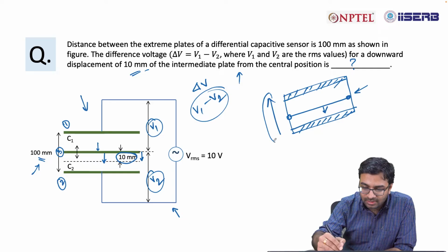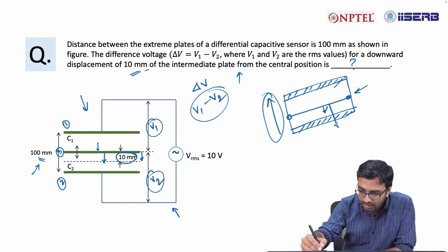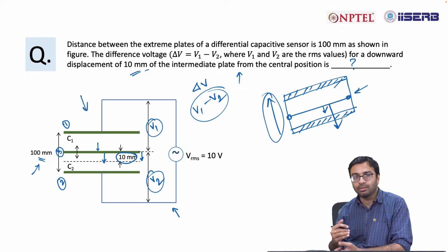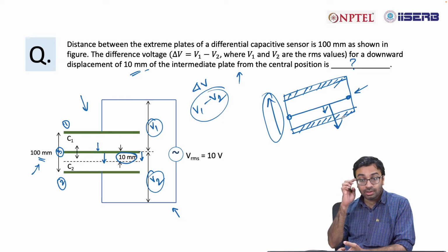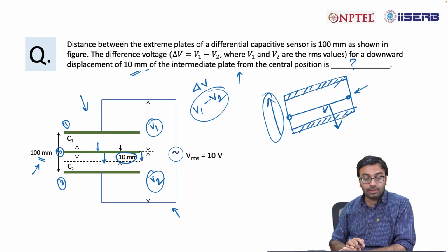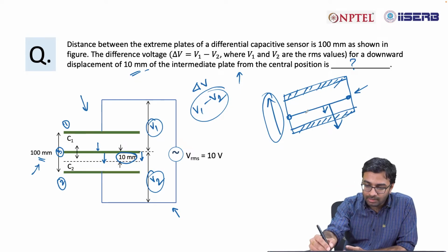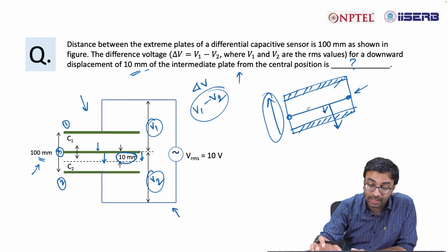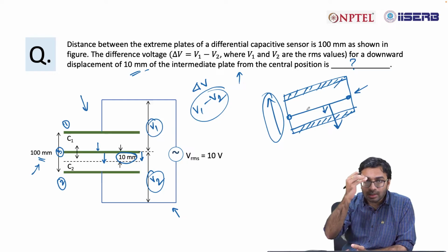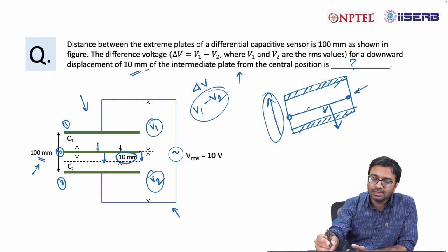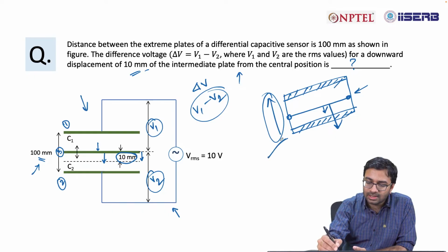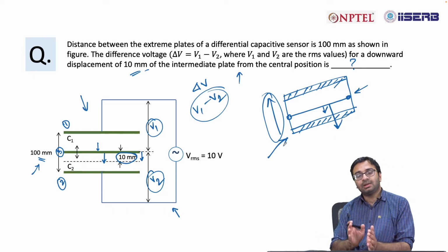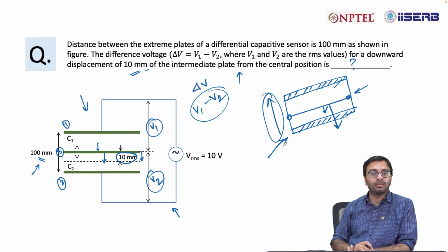Now if the acceleration is higher, maybe this plate will move further down. From that one can understand what the acceleration value is. Because this plate will be in inertia, the moment you start moving the entire system, this plate will come down because it's movable. So that is a kind of sensor consideration that you may consider, which is related to this problem.